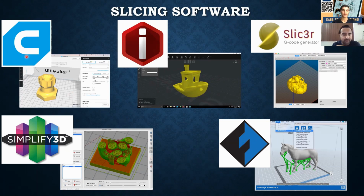So we have, for example, Cura by Ultimaker. You have this one called Idea Maker. You have one called Slicer. There's one called Flash Print. There's this expensive one called Simplify 3D. And the literal only point of these slicing softwares is it takes in your STL file or your 3D file, and then it converts it to what's called G code. And G code is literally just 3D printing language speak for how the printer head should move around the surface and how quickly it should feed in your filament to create whatever structure you're designing.